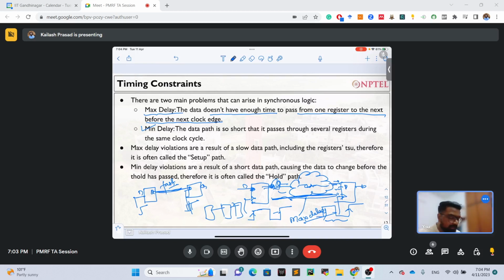Shift register. So if you do VLSI, or if you have a synthesizer tool, and you are designing counters, you should be extremely careful when you design counters and shift registers, because later on there can be hold violation in that. So the examples where the hold violation can occur are the counters and registers where there is no combinational delay between the two flops.